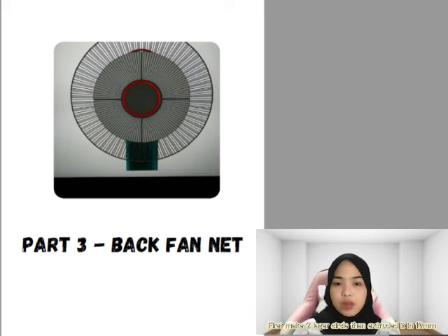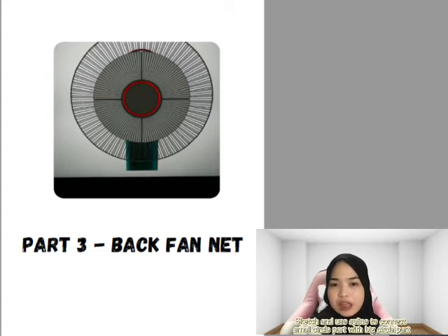Today I want to explain this part, the rear panel. First, make 2 larger circles, then extrude it in 10 mm. Then, using plane and distance from start space, largest inner circle 150 mm. Make 2 small circles and extrude it in 10 mm. Sketch and use spline to connect small circle part with big circle part. Make sure there are circles by using extrude swept boss.